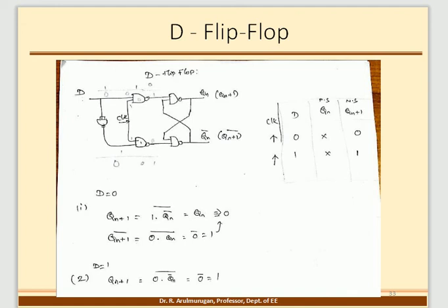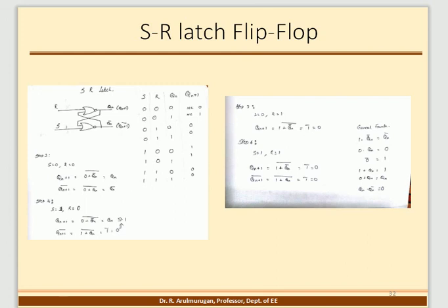It's common. The next one is when you look at the SR latch flip flop. Instead of the NAND, they are using a NOR gate for that. The NOR gate is used with present state, present state bar, next state bar. Here R is used, here S is used. The same four steps: 0 0, 0 0, 0 1, 0 1, 1 0, 1 0, 1 1, 1 1.